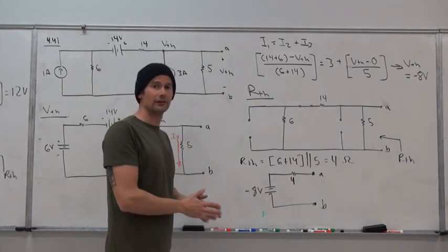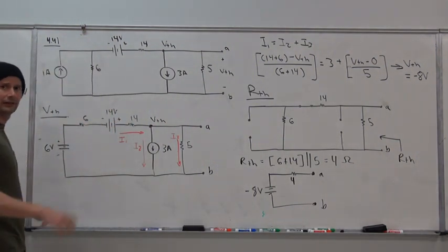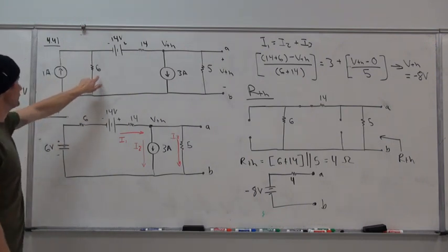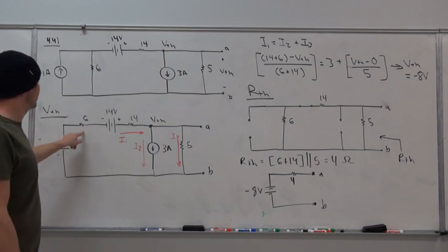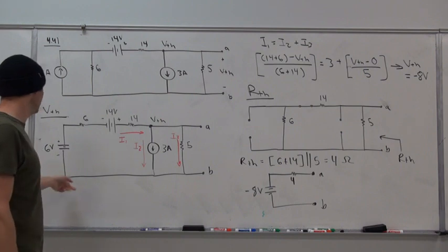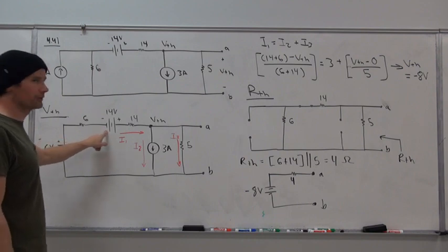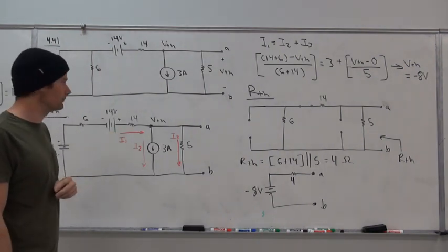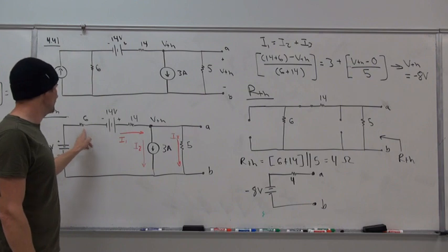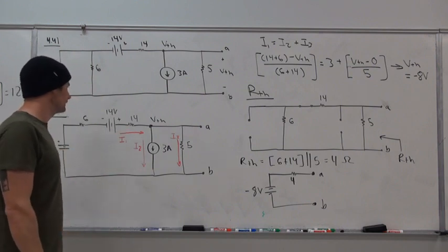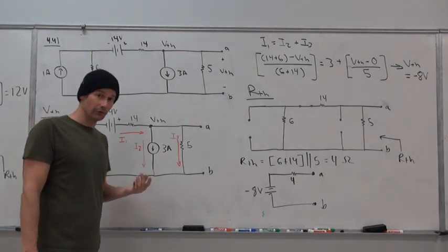So let's first take a look at the Thevenin voltage. Here we can quickly perform source transformation. Let's take 1 amp, take the 6 ohm resistor, and multiply those together. By Ohm's law, we get 6 volts, and that puts that in series with 6 ohms. That gives a series equivalence of 6 volts in series with 6 ohms, in series with 14 volts, in series with 14 ohms. Here we can see that would render 20 volts total, as well as 20 ohms of resistance.